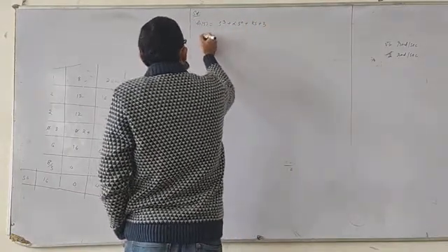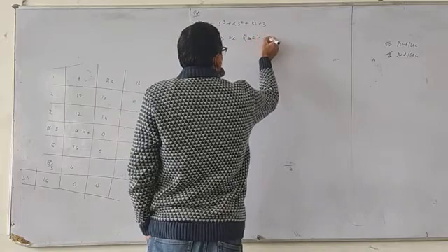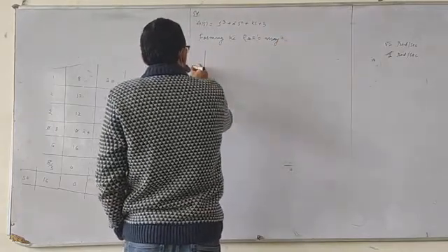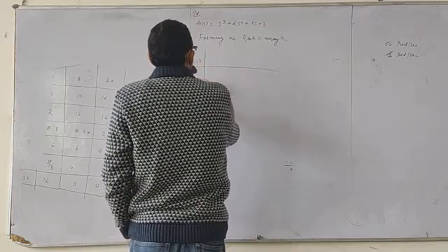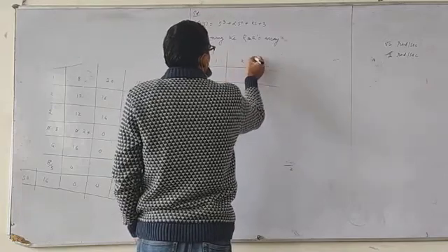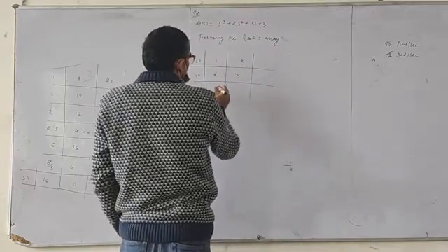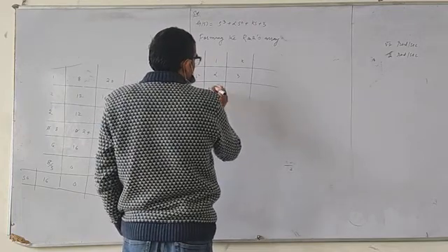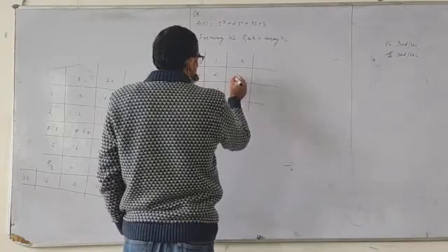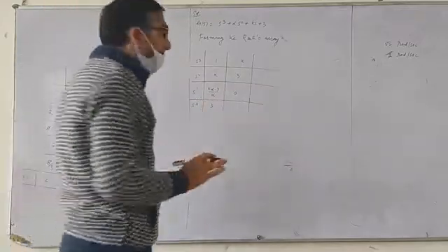Okay, now form the Routh array. S1 will be (K alpha minus 3) divided by alpha, and that will be 0 for the last row. This has to be copied here. This term is multiplied by 3 minus 0, divided by this, which is 3. This term has to be copied all this way.